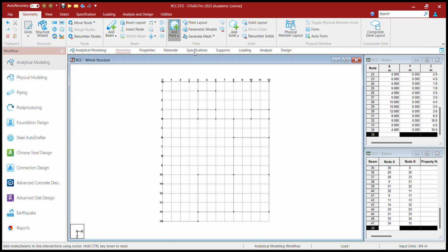So we'll use perpendicular intersection from this position on this beam. Okay, now here we need to create one beam here, and then we'll add this one. So for that we'll go to this distance, it is 3 meter. So from 8 point you need to create it up to 3 meter, 15 meter, and then we'll join this. Okay. After that, the next position it is directly to this beam. This one is done, we need to put one in the middle at 2 meter center.